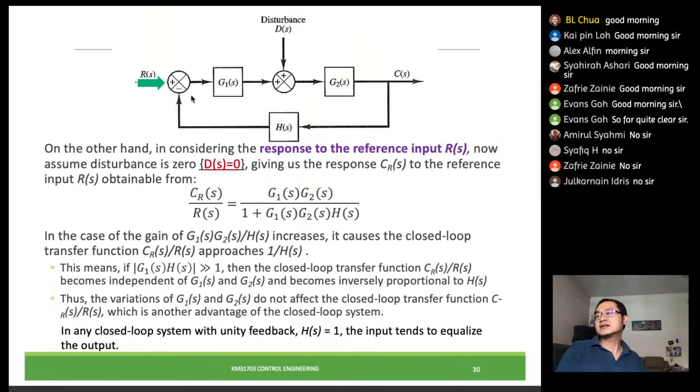After that, we now want to see what actually happens without disturbance. This is the original form. So with respect to the input itself, the R input itself, what would happen? It would be very straightforward. These two cascade together in series form, and then we can recognize the feedback control loop. So we can have G1 G2 divided by 1 plus H G1 G2.